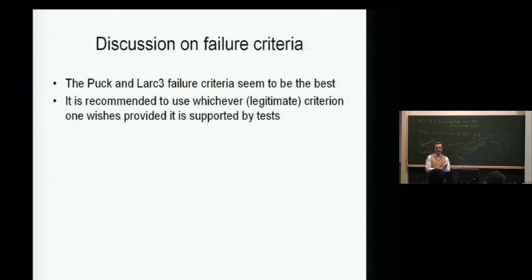I recommend any version of the maximum stress, maximum strain, or my personal favorite, which is the one that's been attacked the most, the Tsai-Wu criterion. Those I have programmed into my computer, and those are the ones to check your results. But if you use a different one, that's fine.